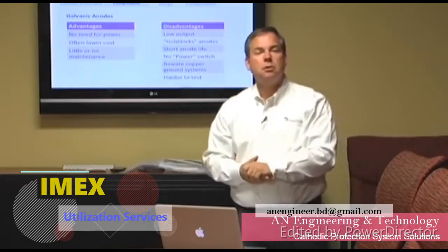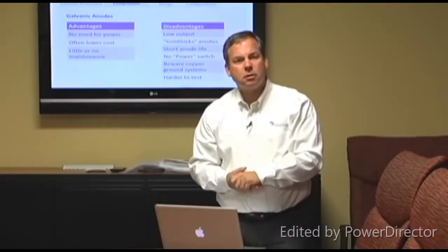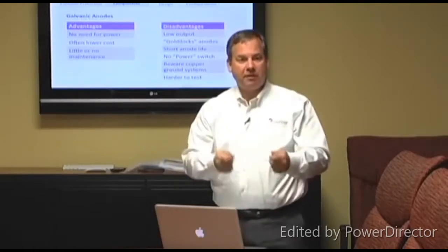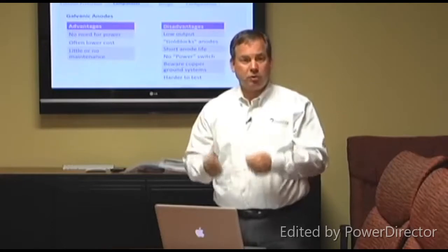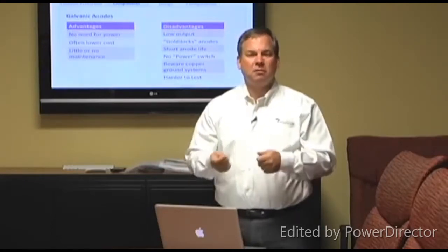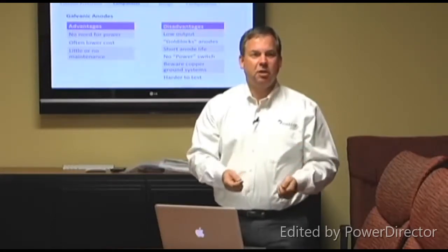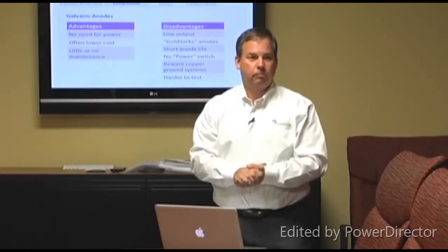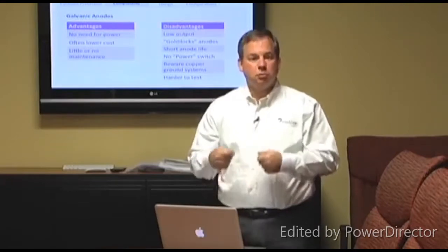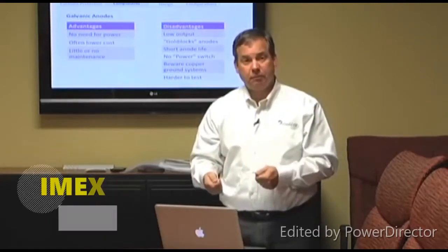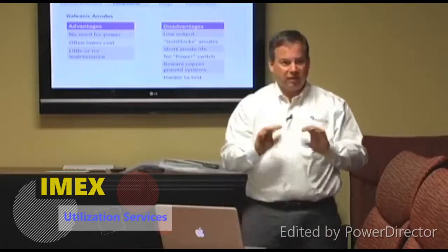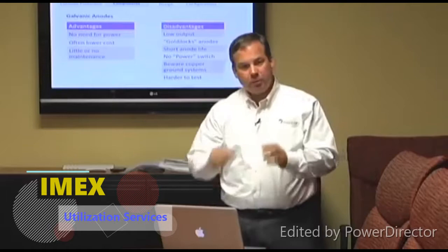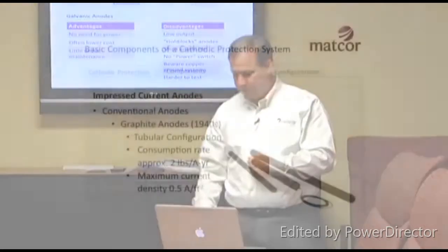Yes? Wouldn't, if you build a test station into the galvanic anode, wouldn't that take care of that? You could put test facilities in for galvanic anode systems, and when we design galvanic anode systems, we do that, but it does require some level of sophistication to test it above and beyond just looking at a power supply and saying, yes, it's still where it was last month. Okay? So with those systems, you do require a little more sophistication in testing them. But yes, we do definitely, I mentioned earlier in components, you want to have provisions for testing. But generally, they run until they're consumed, and then they fail.